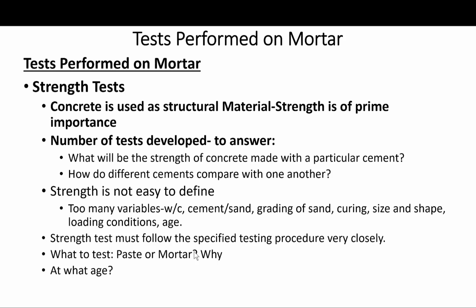In addition, though, for high early strength cement, type 3, there is a 1-day requirement, and for low heat cements, type 4, which hydrate slowly, we may sometimes require a 90-day requirement as well. The requirements of ASTM C150 are shown in the table I showed at the beginning of the lecture, table 3.10 from ASTM.